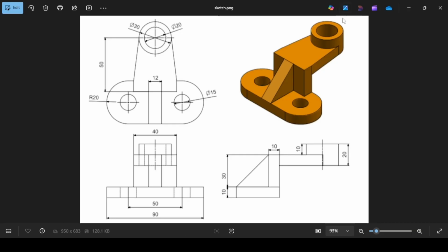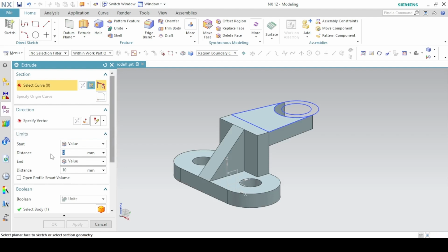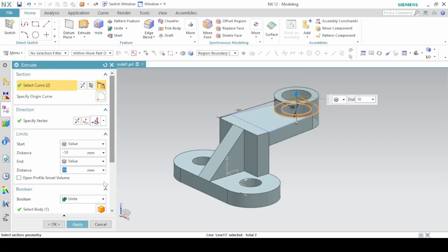Then you're going to extrude this cylinder. So since we made the sketch on this face, which is over here, you have to start the extrusion at an offset distance of negative 10 millimeters. So the extrusion will start on this face and end at a distance of 20 minus 10, which is the 10 over here, so that the offset distance of 10 millimeters plus this actual distance of 10 will give us 20 millimeters for the whole height of the cylinder. So we start the extrusion at an offset distance of negative 10, and then we end at a distance of 10. Now click on this region between the inner circle and the outer circle, and then click OK.